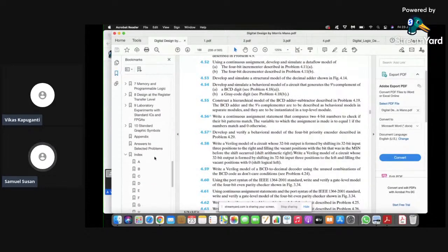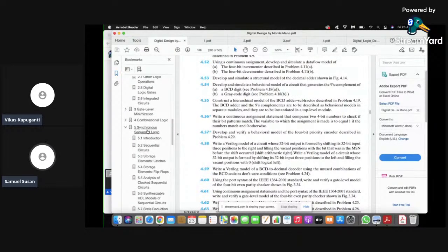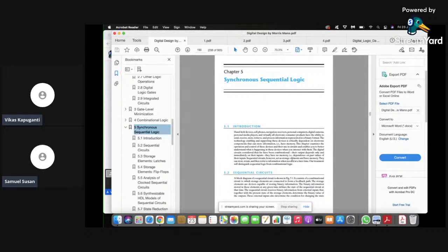We need to be thorough with the circuit diagrams for the four flip flops: JK, D, T, and SR. The first one is actually SR. After analyzing the circuits for those four flip flops and their tables, that is the characteristic table and the characteristic equation of each flip flop, you will be asked to design a sequential circuit, provided either a state diagram or state equations. Mostly the state equations will be given in terms of A of t plus 1 and B of t plus 1.